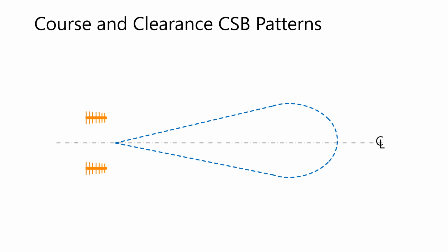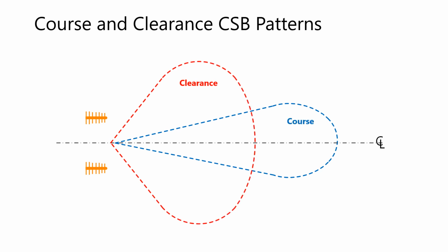So to overcome these problems, the course signal must be narrowed, and a second RF pattern is radiated to mask these side lobes. An additional transmitter is used to develop this pattern at approximately 10 dB down from the course. Together they are known as the course and clearance, with each containing its own CSB and SBO signals. In 14 and 20 element arrays, these clearances are radiated from the inner 5 pair, known as a 1410 or 2010 array.